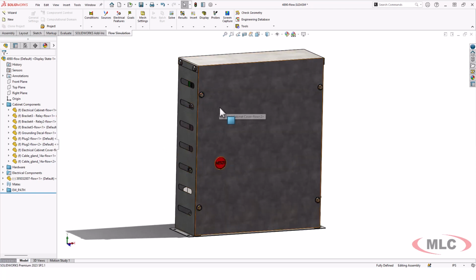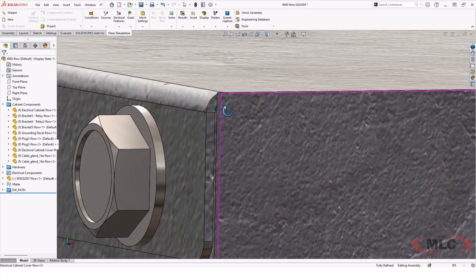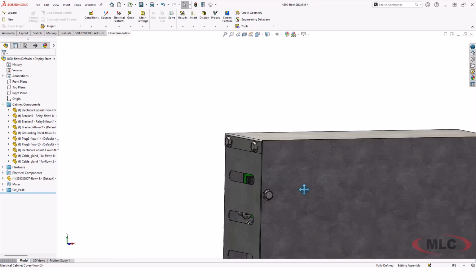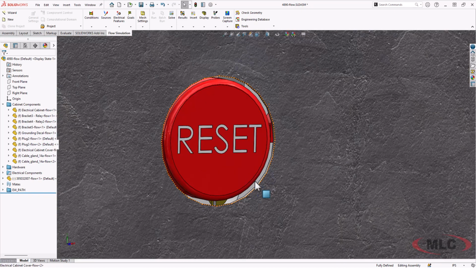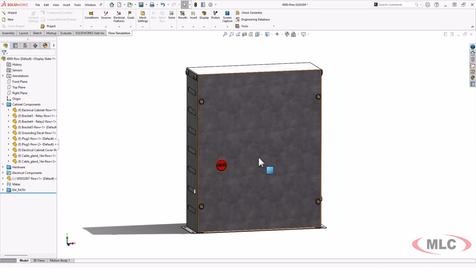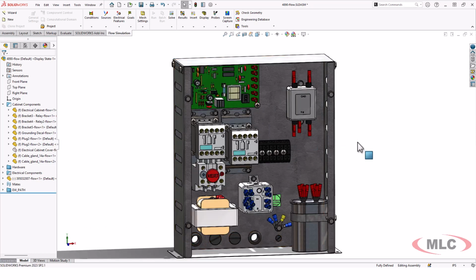Now, this is sheet metal, so we already know we're going to have a problem with leaks kind of in the corners where the bends don't quite overlap. And in fact, this one, if you'll look even in this bottom, there's like an opening here. So we've got a lot of geometry preparation to do. Let's take a look inside and see we've got a lot of complex shapes.